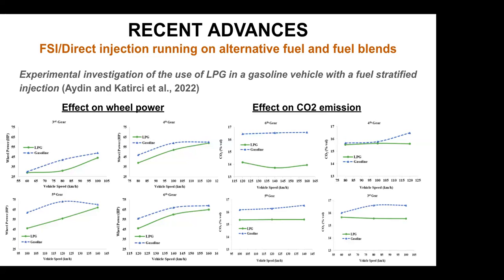When gasoline and LPG fuels are evaluated in terms of energy values on a liter basis, this can first be explained by the fact that LPG gives 30% less energy than gasoline. Secondly, LPG fuel occupies more space because it enters the combustion chamber in gaseous phase with the air in the engine intake manifold. This problem can be fixed by increasing the compression ratio of the engine. However, this is not possible with atmospheric engines. The engine has to be redesigned.